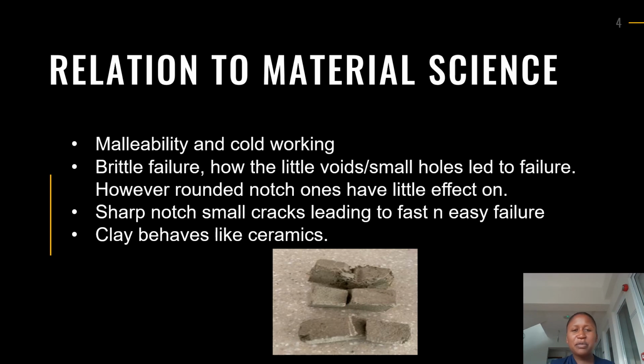So, our relationship with material science, we had a chance to learn about malleability, and it's as a result of cold working. We also had to learn about brittle failure and understand how the little voids or small voids can lead to failure. And we also had a good time to discover how rounded notches have little effect on the failure of a brittle material compared to the sharp ones. Because we discovered that with some of the bricks that we have, a small crack was actually leading to the failure of the whole brick, like breaking into half for some of our samples.